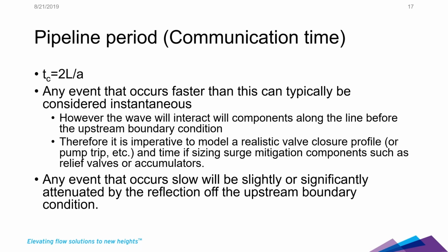And that will allow you to say, okay, my valve closure happens in 30 seconds, but my system is this long, my average wave speed is this. Is that valve closure effectively instantaneous? Am I going to have a chance for the upstream boundary condition to relieve the pressure rise, to communicate itself back down to my closing valve that, hey, I'm still here, this is my pressure, I'm going to force that upon the system? Or does it not even have a chance? Does it not even see that pressure wave before that time? That's going to be a critical thing.